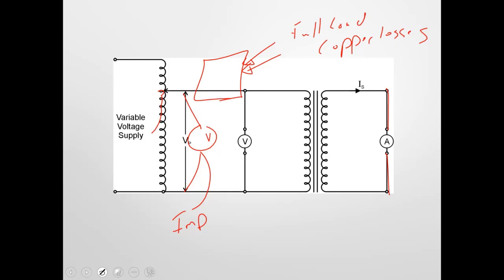Okay, so onto this impedance voltage. Say we're at 10 volts, and this is a 240 to 120 transformer. We could calculate the percent impedance of this transformer. We say it like this: percent IZ or percent Z. It's usually stamped on the nameplate, but we're going to be doing some testing where we can calculate this. Percent IZ is equal to the impedance voltage divided by your rated primary voltage,